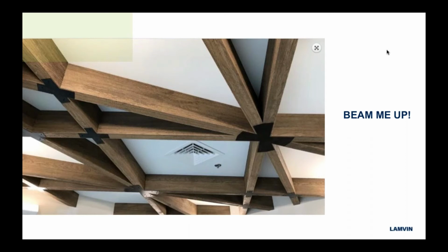It should be noted this can often be accomplished with a vinyl finish or perhaps a thin wood veneer. Keep in mind the finishes, like perforated vinyls that are appropriate on acoustical products, make them suitable for areas that require more maintenance. Factors to consider include cleanability, wipeability, even bleachability to kill bacteria, or for spaces that have moisture issues or abrupt changes in humidity.